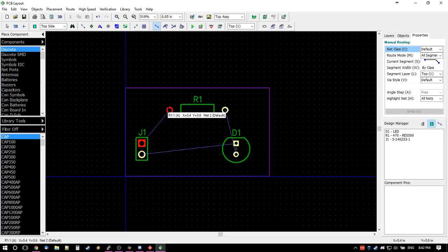That shows this is what you want connected together. So click on the resistor. Then the nice thing about the routing is that it'll take care of the angles for you. Now, that's a bit ugly. Typically what I do is I sort of come over like this so that we get a nice angle in it and then go straight down. And that's it routed.